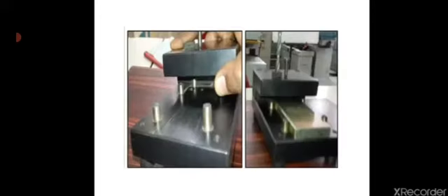For the location of rough surfaces, adjustable type locators should be used, and to avoid distortion of the workpiece, it is properly supported. Again, sharp corners in the locating surfaces must be avoided. For easy fall of chips and burrs, locating surfaces should be raised above the surrounding surfaces of the jigs and fixture. Now we will discuss various types of locating devices.